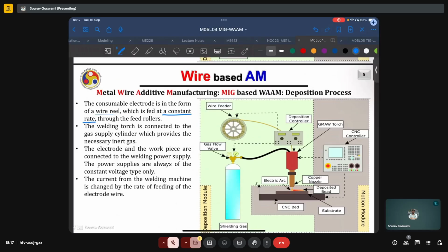Typically it will be argon, but there are studies where they have varied the composition or the type. It need not be one single inert gas, it can be a mixture of them in some particular ratio. And studies have evaluated how changing the inert gas changes the deposition characteristics.